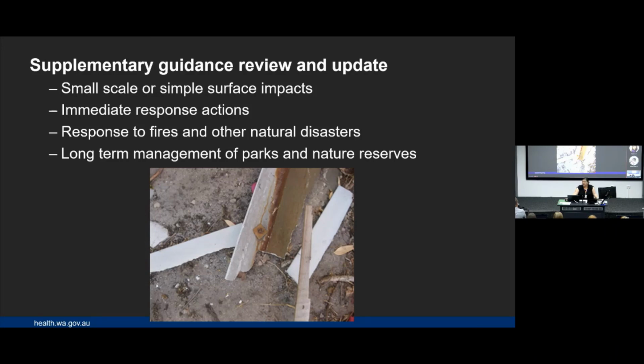But yeah, understand who your receptors are, understand what work is happening at the site, and understand what your material is and whether or not it can produce fibres in air to an extent that people are exposed above public health guidelines.